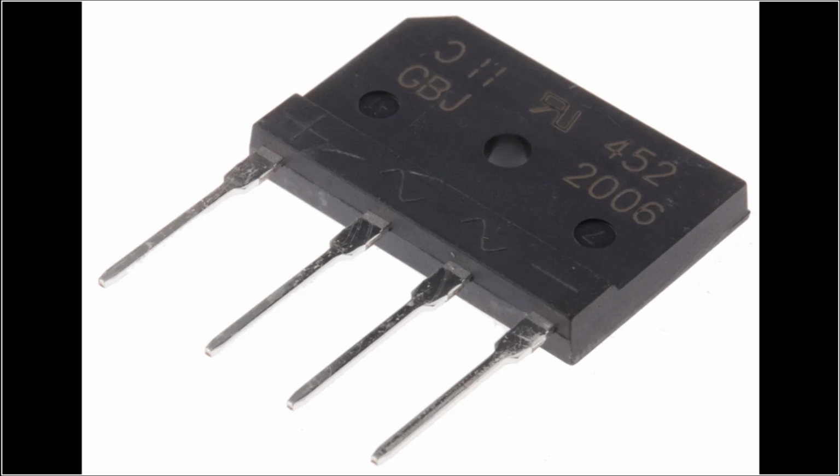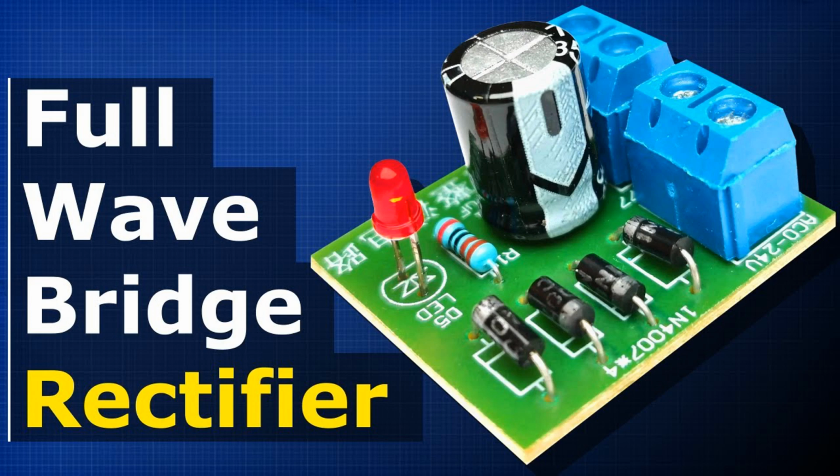Filtering and regulation. After rectification, the DC output of the bridge rectifier may undergo additional filtering and regulation stages to further smooth out fluctuations and maintain a constant output voltage. This ensures that the power supply delivers a reliable and consistent voltage to the load. Voltage transformation. In some cases, power supplies may incorporate transformers before the bridge rectifier to step down or step up the voltage from the mains power source to the desired level. The rectified DC output voltage can then be further regulated as needed.